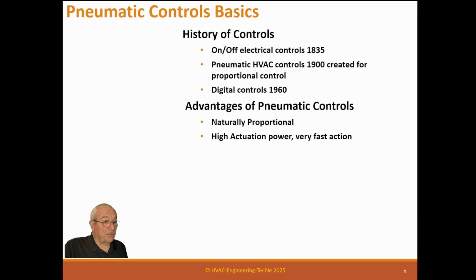If you're trying to catch a pressure wave, which is moving in a pipe at 600 miles an hour, you're not going to do it with electric. You're just not. You're going to either have to have hydraulic or you're going to have pneumatic.